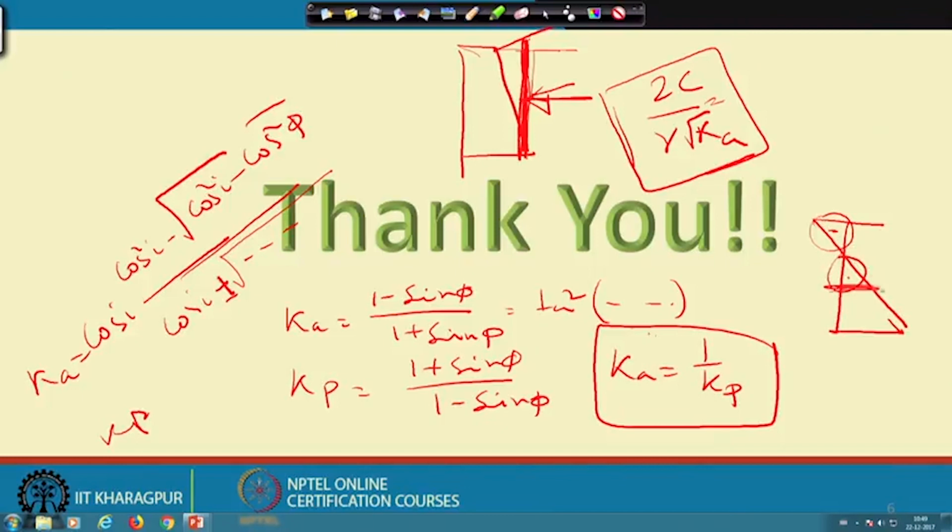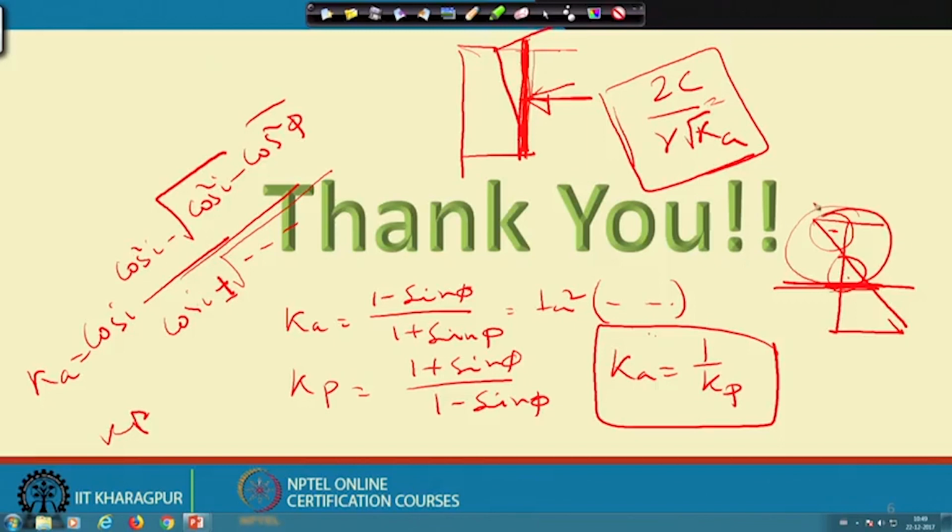That means up to this depth on the wall the net effective pressure is 0, so up to this depth we can cut without any support. There you have to multiply by 2 to get the actual depth. This is the way we have done it all. I hope this is enough and it will be useful for you. Thank you.